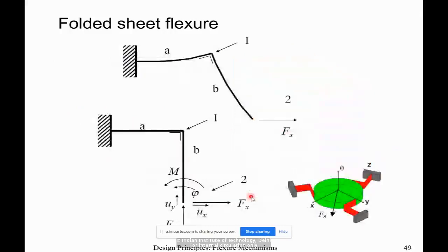And they are used in various applications. One of the things I discussed with you earlier is you can design a very good planar stage, which can give you displacement in x, y, and theta rotation, right? X, y directions translation, and rotation in z direction, but only motion in a plane. And it's much better than three wire flexures because there is no shortening effect.